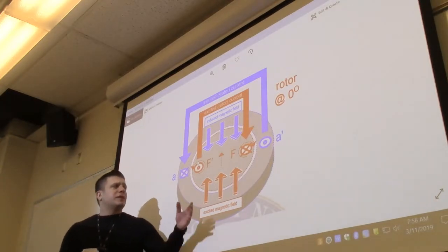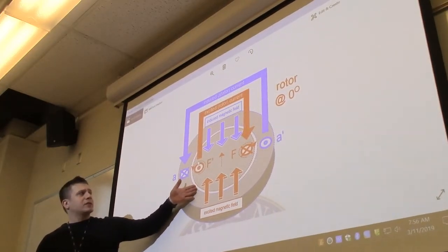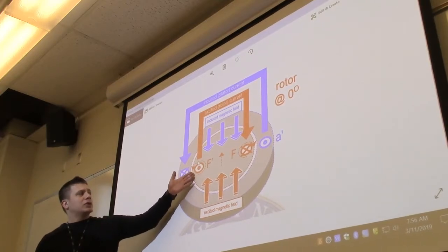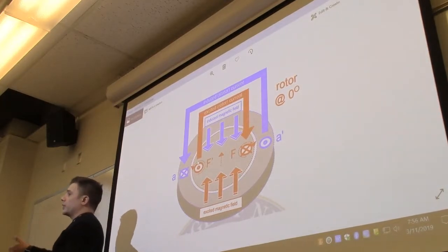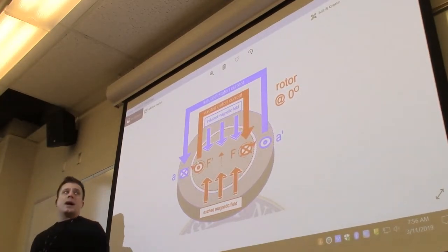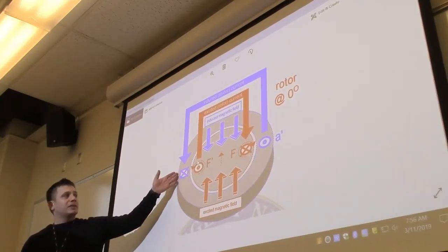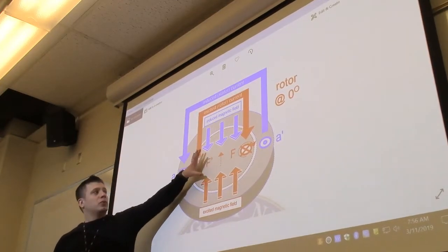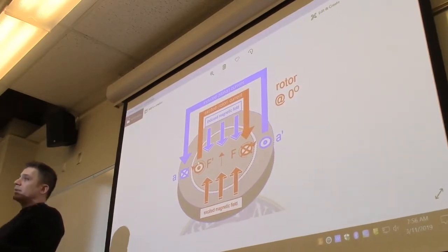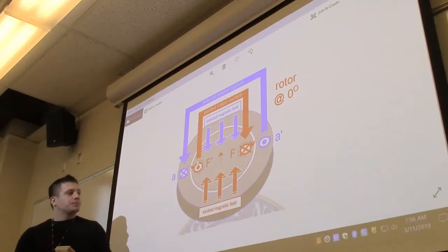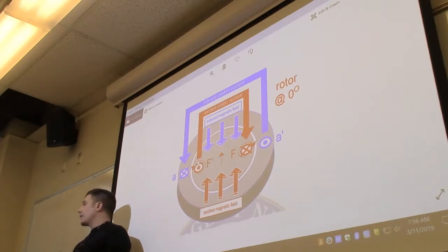And then here you can also see physically what's going on with respect to the directions of the currents and the directions of the magnetic fields. Right? We can use right-hand rule to show that the red arrows are the magnetic field that would be generated by the current in red. The excited or induced stator current has a direction that is opposite to that, again following right-hand rule, and what we see is in the end these two magnetic fields sum to 0. Okay, and so that is really a good explanation of the way that a synchronous generator works.